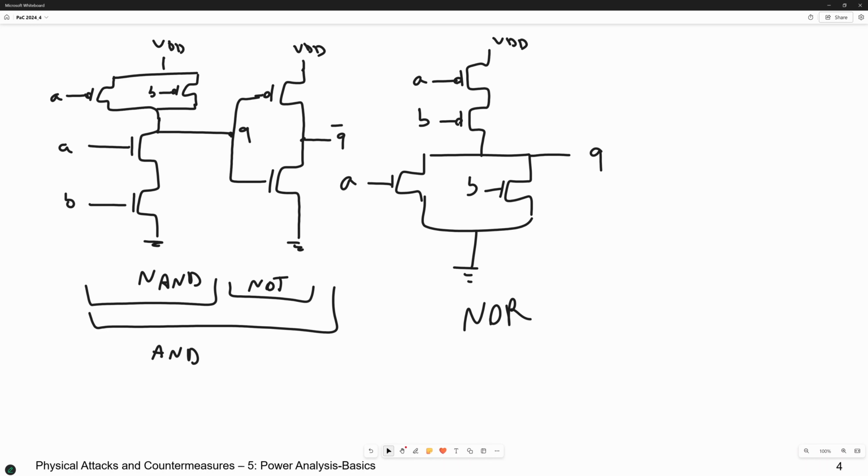The problem is that you don't have any chance to build such CMOS gates, for example an AND gate, by one stage. You know? Always the delay and the size of a NAND gate is smaller than the delay and the size of an AND gate. The same for NOR and OR. XOR gates are completely different. They are much larger, but usually there is no difference between XOR and XNOR. The size and the delay of XOR and XNOR are roughly the same. Good, that was a bit of digital circuit design.